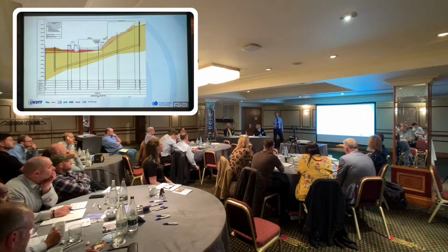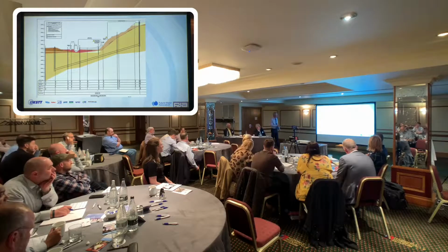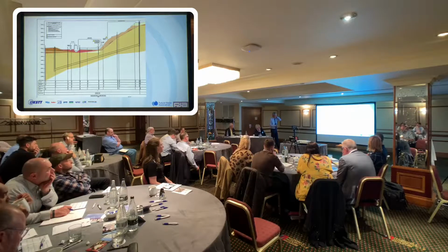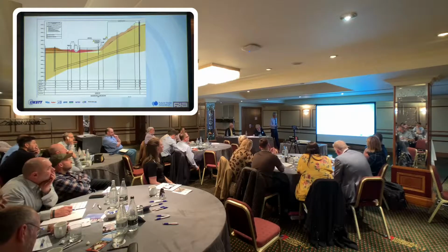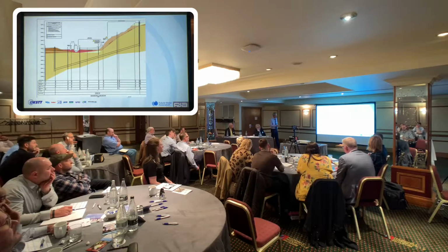This is the right cross section. So this is the cross section, very deep shaft in sandstone with its constraints of dealing with groundwater at depth, river with superficial deposits, a very steep drive to an equally deep reception shaft. By bringing that to here, we would have probably saved £1 million, but the constraints wouldn't allow that.